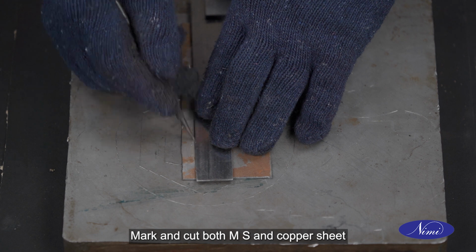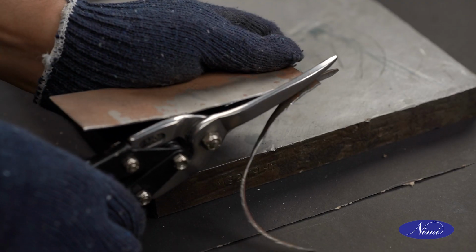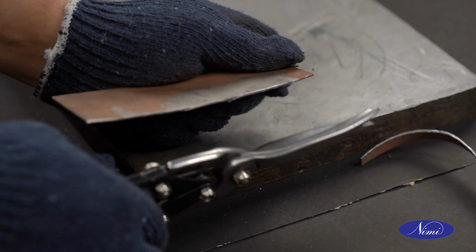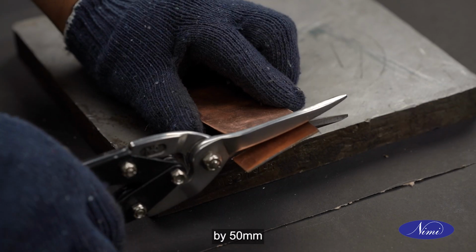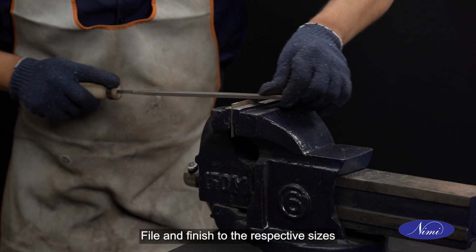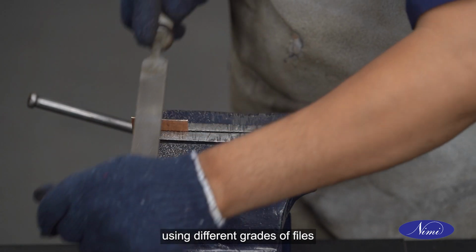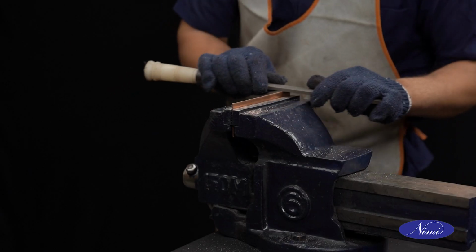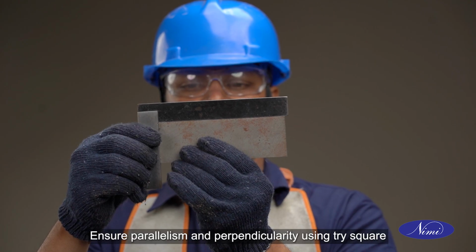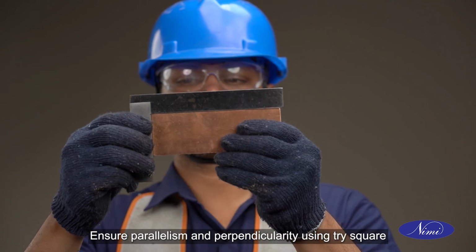Mark and cut both MS and copper sheet to a size of 150 mm by 50 mm. File and finish to the respective sizes using different grades of files. Ensure parallelism and perpendicularity using tri-square.